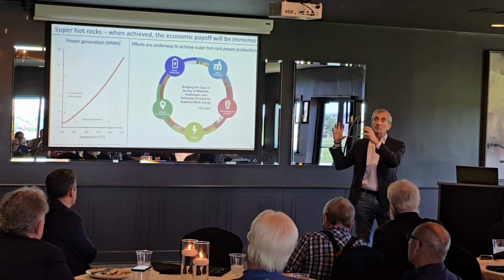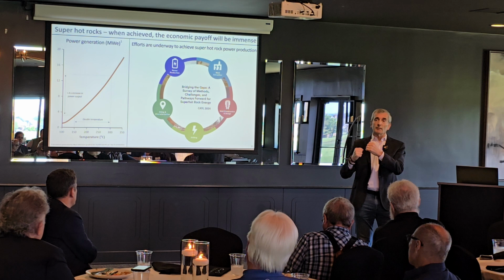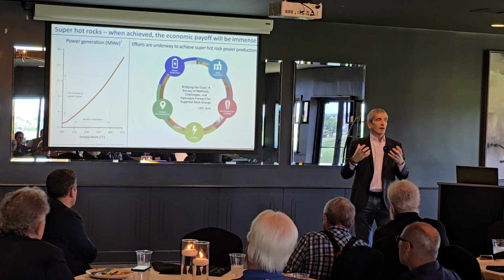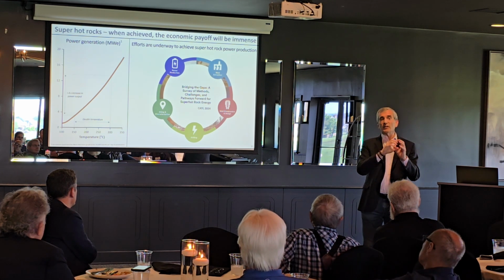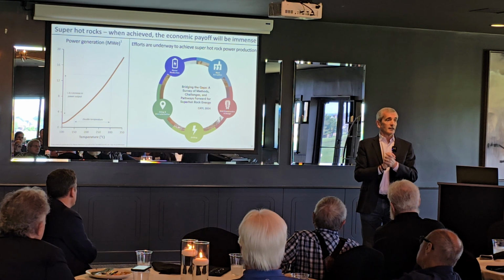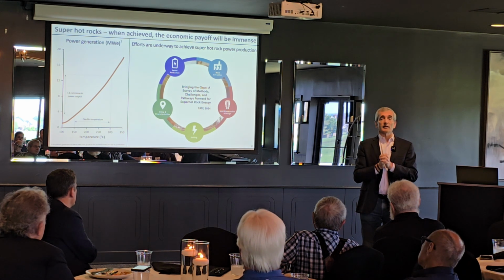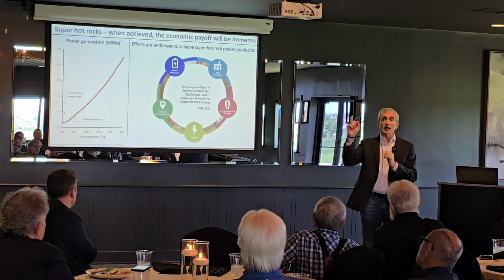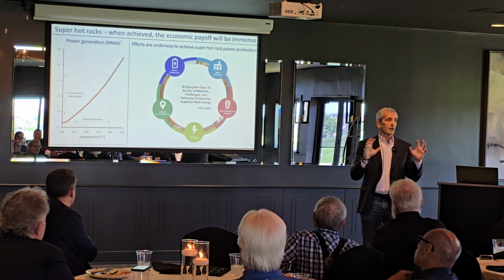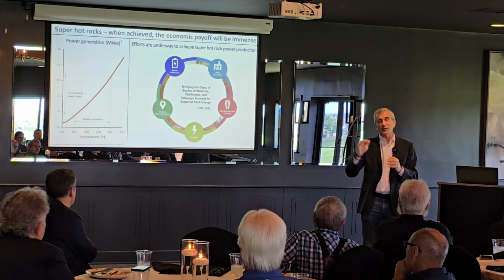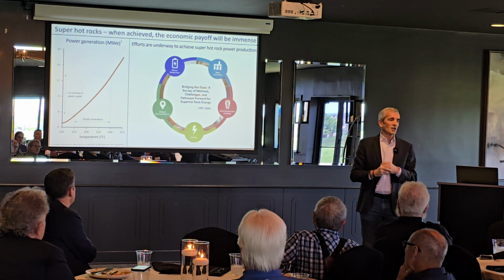Rocks do not transmit heat very quickly by conduction. So you can cool it down. If you cool it down, you can actually use oil field equipment at 400 degrees Fahrenheit, 500 degrees Fahrenheit, and there's even a company out there trying to do it at 600 degrees Fahrenheit with nothing that isn't, quote unquote, off the shelf, although it's the high-end off the shelf stuff.